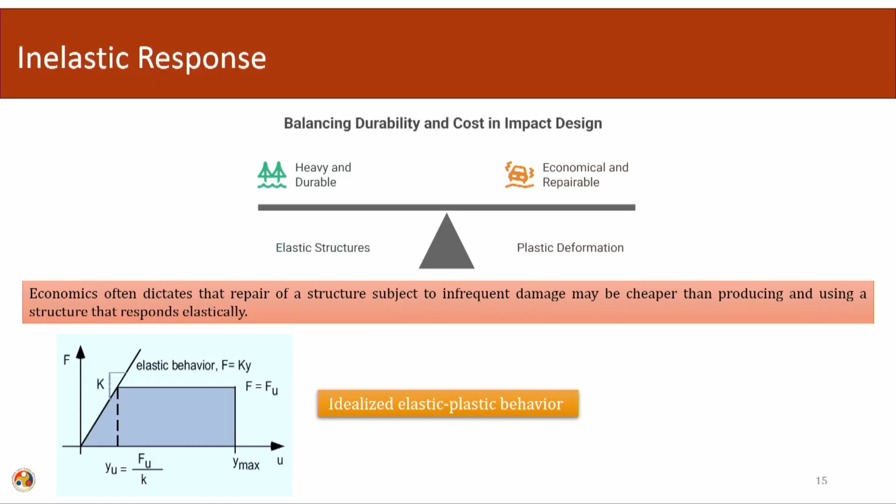more. So, what I can do is allow some plastic deformation, and then it will bring down my force demand. That way I can optimize my structure while allowing some plastic deformation. This is the principle that is used normally in the design process, where some plastic deformation is allowed to achieve an economical structure.